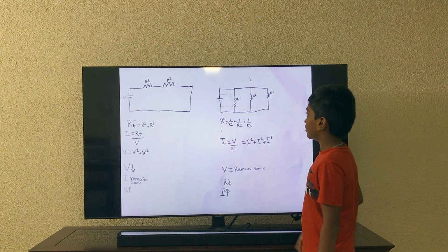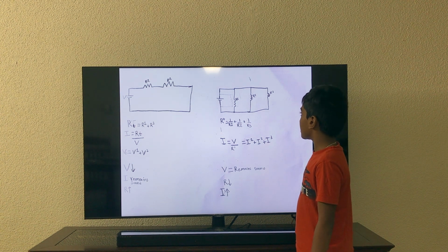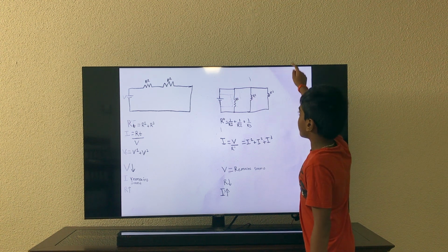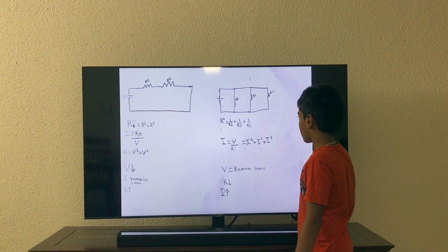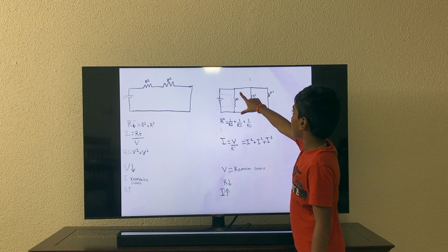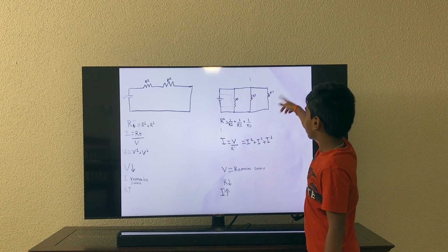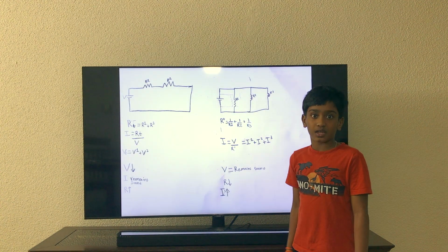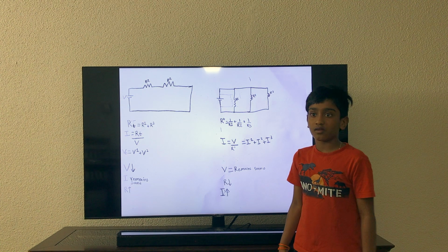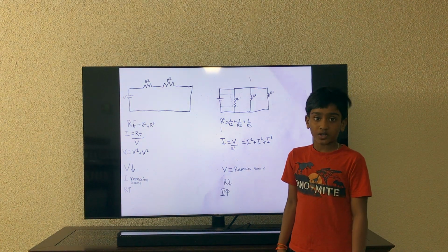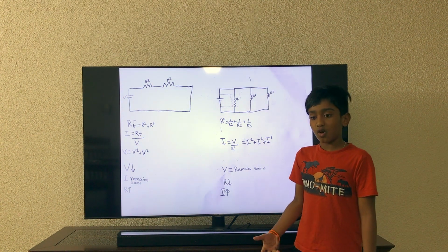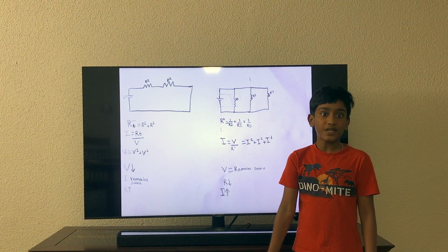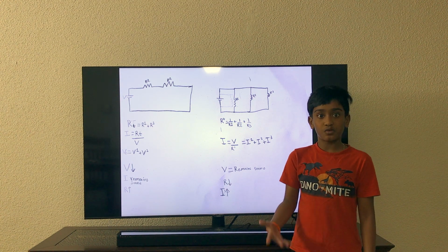This is a parallel circuit. In a parallel circuit, each component has its own path. So R1 has its own path, R2 has its own path, R3 has its own path. If I take one of these out, the others will still be glowing. Parallel circuits are used in our houses. So if you switch off the light, you can still watch the television. If your home's appliances were connected in series, you would have to switch on everything to use one thing.